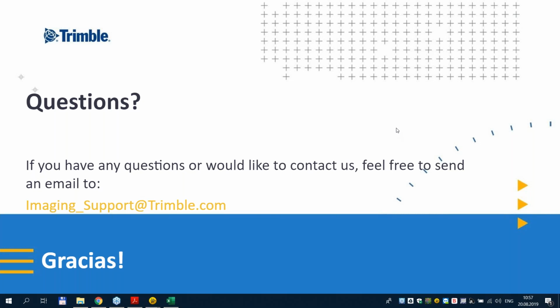That's a good question. Miguel, will you want to answer this one about relative registration? Yeah, for the relative registration, the most important thing is that you should be able to identify the tie points, meaning both of them should be visually and easily identified between the two runs. We also have an adjustment and interpolation in this computation, you should distribute it equally in between the scans.